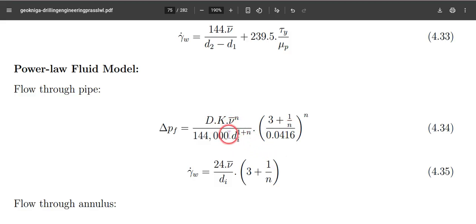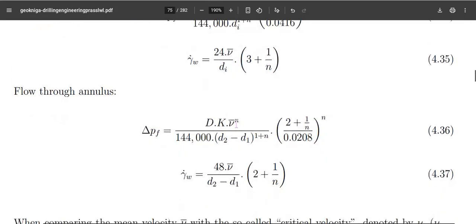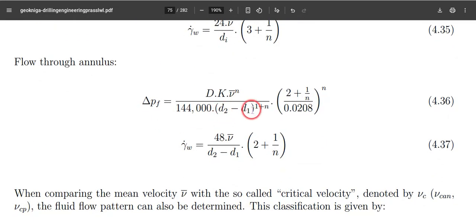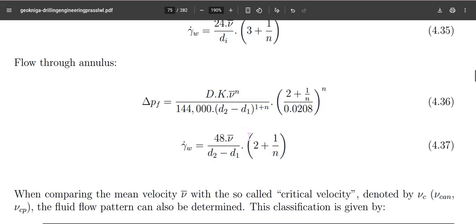and the k value, which defines the physics of how thick the viscosity of the fluid would be. So based on this k and this n, the more the k, the more the friction loss, it will give you this nonlinear formula based on that flow behavior index. And this also gives you nonlinear relations between the frictional velocity and the pressure drop based on the behavior index. It can be from 0 to 1 as mentioned in the last lecture. And similar to the annulus, same thing, only the geometrical properties differ, and it's almost similar to that of the